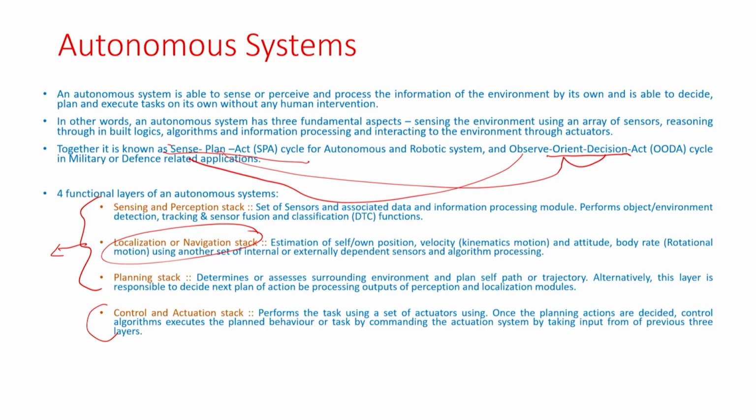That is important to process your sensing or perception function. Once you have processed it, they are raw data. Now, the sensor is giving you raw data. Raw data will be contaminated with noise, and there will be clutter. Clutter means I can see a false target. Your sensor is saying there is a target here, but actually there is nothing. This is a false detection.